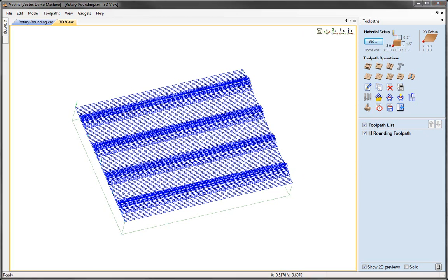Once you've matched that setup to your particular machine and the size of job that you're planning to cut, then really it's just a case of creating standard toolpaths in order to generate the part that you want to machine, even though one of those linear axes is being wrapped around the rotary. As we discussed, if you're using VCarve Pro, you can't actually preview those toolpaths. All you can do is do that rotary drawing and see how the toolpaths themselves will be oriented once they're rotated around the cylinder.